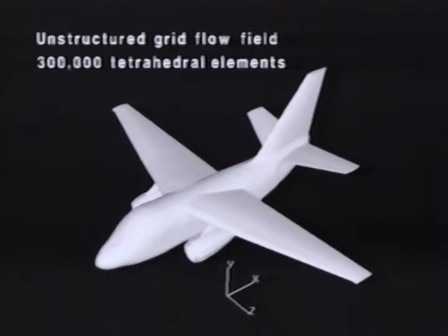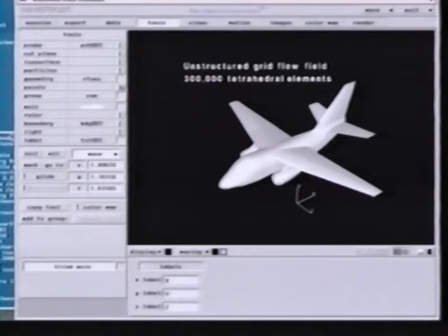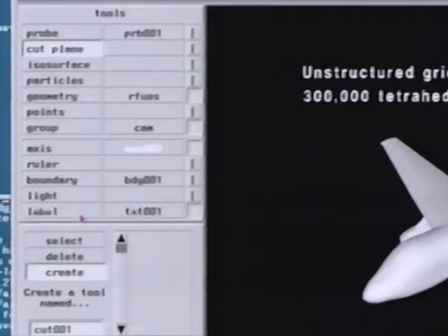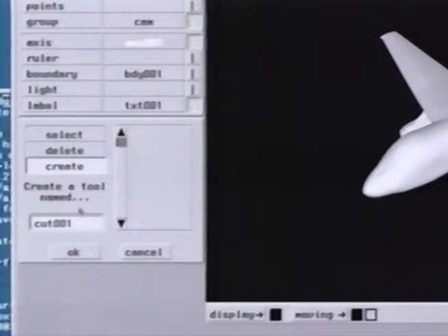Our last interactive example comes from a very different family of mesh generation and flow solvers. This is a large single-block unstructured grid solution. In its initial form, the grid consisted of over 900,000 tetrahedral elements. For this analysis, much of the far field has been stripped away using the Data Visualizer's interactive volume of interest capability, which we'll discuss further on. This has effectively reduced the data volume by 2/3 while maintaining full local resolution.